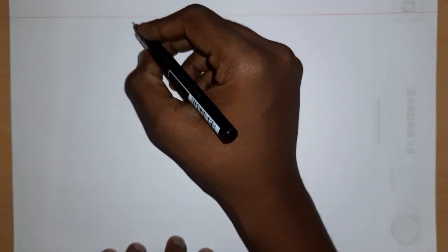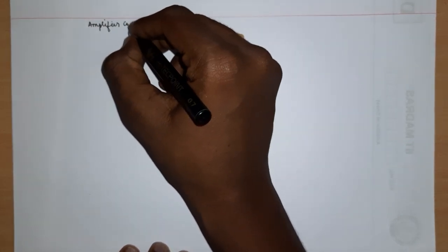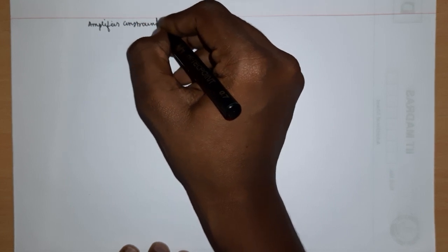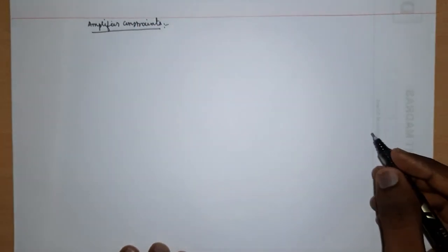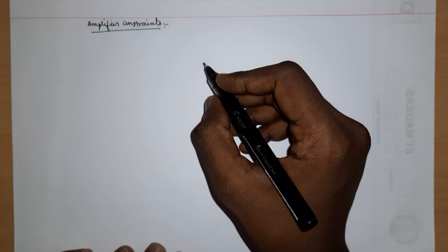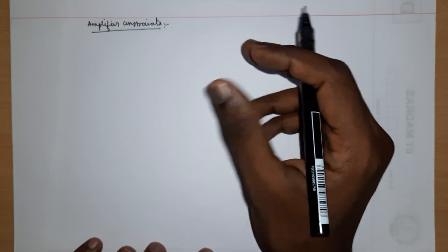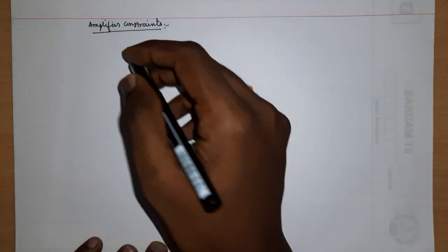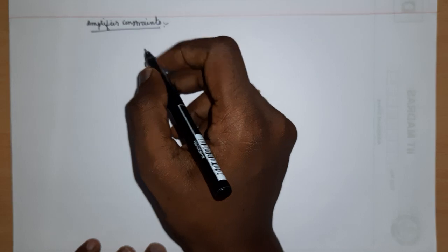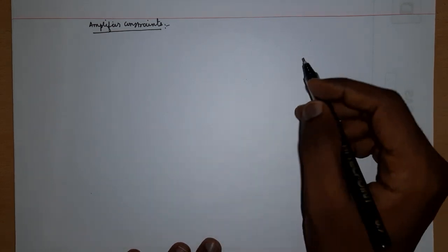In this lesson, we'll discuss the amplifier constraints. So essentially, we introduced the two-port network, and then we talked about linearizing the two-port network using Taylor series. Once you neglect the higher-order terms and take only the first-order term, you will get a linearized form of a two-port network, a linear two-port network, which you have done in your basic networks course or basic circuits course, and you know how to deal with linear two-port networks.